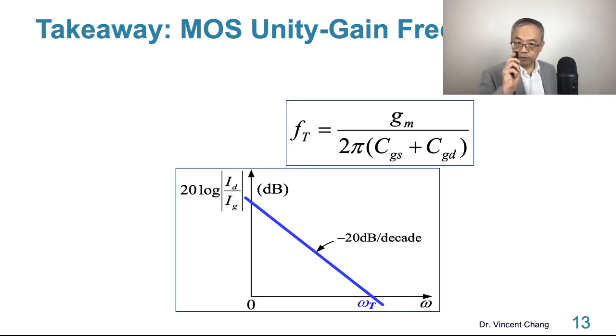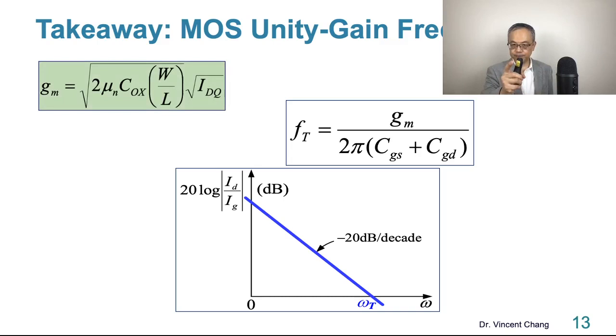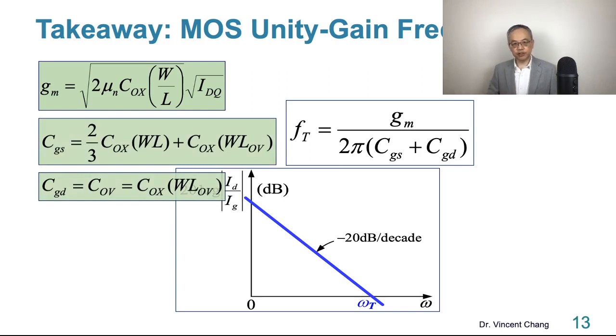But because this is a course for semiconductor device physics, if you have some foundation around this, now you know not just this, the geometry, mobility, gate oxide capacitance, bias current, but you also know this. So you can understand if someone asks you, if we increase the bias, how will this impact its frequency limit, ft, then you know how to answer.